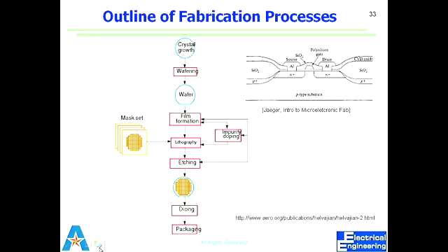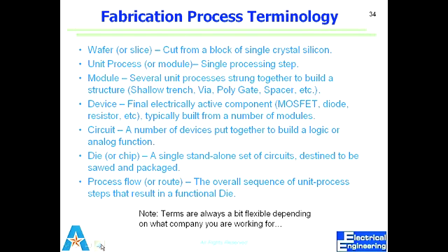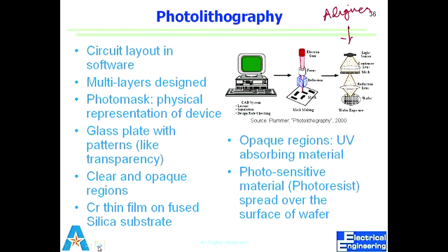What is lithography again? We use these transparent media, which can be a glass plate, to define regions of opaque parts and transparent parts, and we shine light through it. That results in a shadow on a wafer, which is coated with a photosensitive material that translates that image onto the surface of that wafer, and we do whatever process comes after that. So again, we have looked at this. What does lithography do?